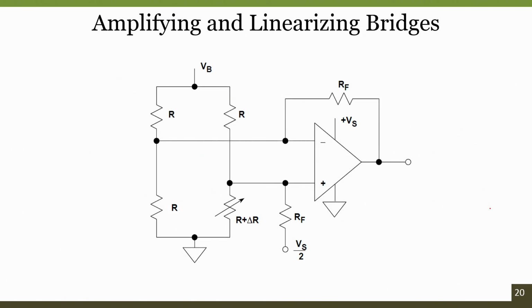So, as we discussed, in order to meet the properties of the next subsystem, the input impedance of the next stage should always be higher, so that no current will be drawn from the preceding stage. So, in order to have a very high input impedance using operational amplifiers, if we connect the output from the preceding stage directly to the input terminals of an operational amplifier, it will have a very high input impedance, so that no current will be taken from the previous stage, which means from the sensor side. Otherwise, the current drawn from the previous stage entirely depends upon the input impedance that we have designed.